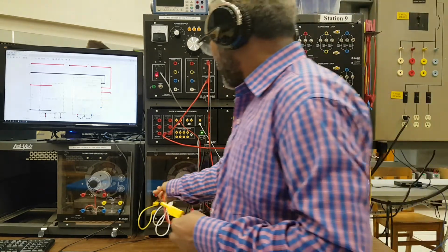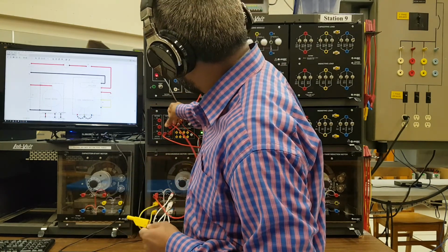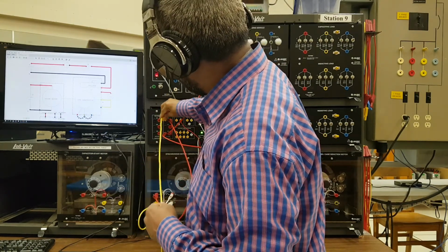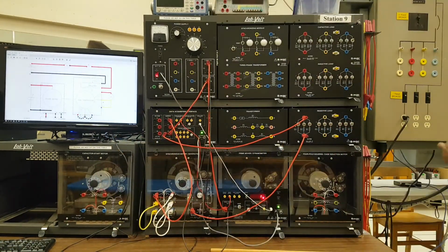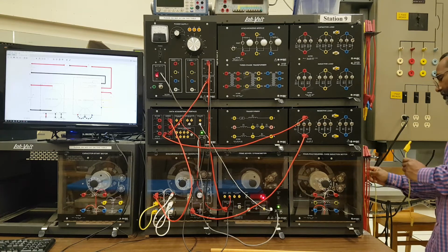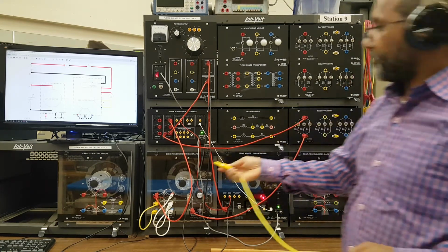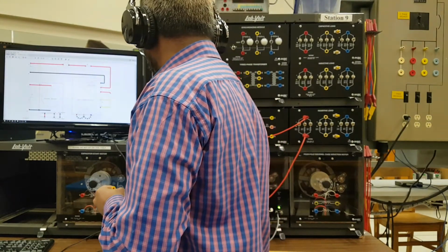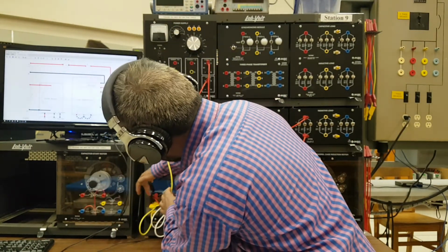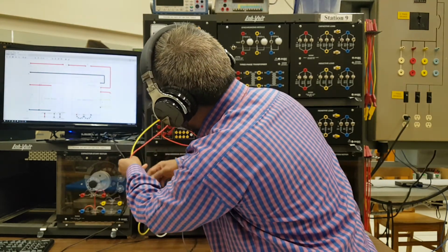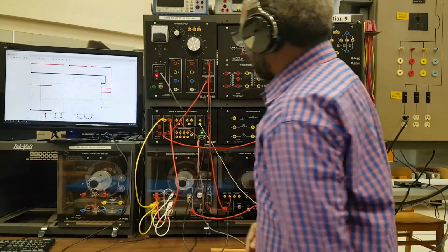So from here it goes to ammeter I1, and then from there it's going to, oh, this is too long a wire, maybe we need a short or medium wire at least. So this one should be connected here. So basically this winding 1 and 2 terminal is shorted through the ammeter, which offers very low resistance there.